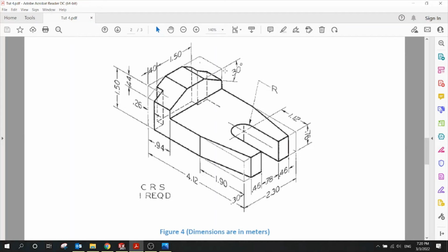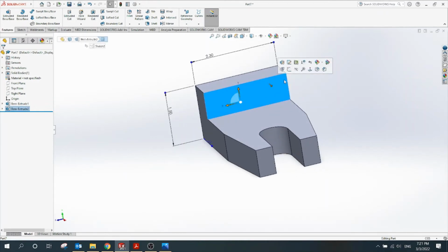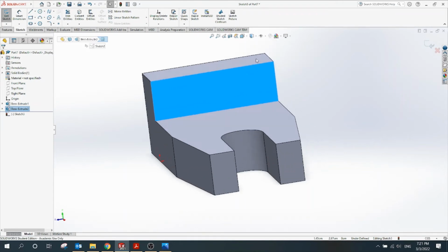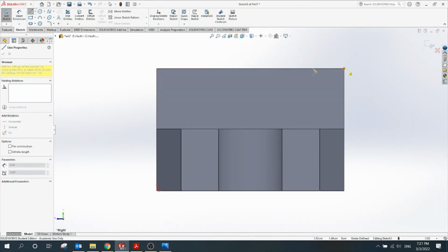So this chamfer, I have the angle 30 and I have the total length of the shape, but it's easy for me to also look at this 0.44. So I can open SolidWorks and create a sketch from this direction, saying new sketch, and this is my right view, and I can create the rectangle. So going down the small distance and the long distance, and then I have to close it.